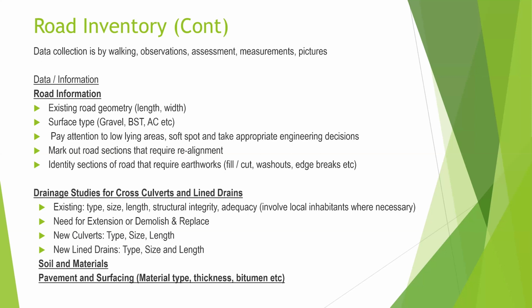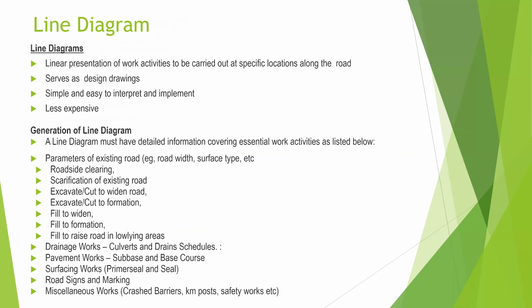Now, for drainage studies, you also have to pay particular attention to the existing drainage structures in terms of the type, the size, the length. Where necessary, you need to extend, you need to demolish and replace. All these things are considered. And then side drains that are so weak and damaged that you need to demolish and replace, you need to take note of all these to make sure that you have comprehensive data to be able to prepare an adequate project for execution.